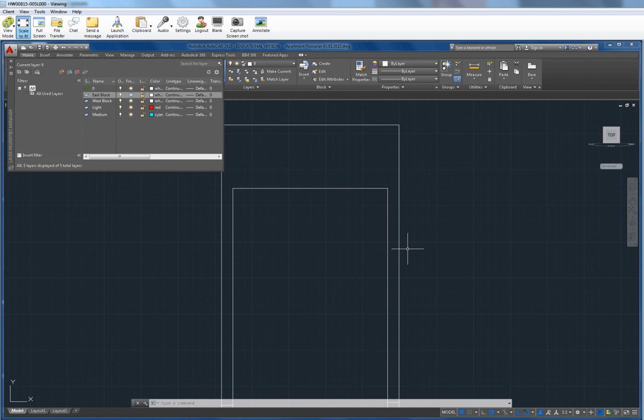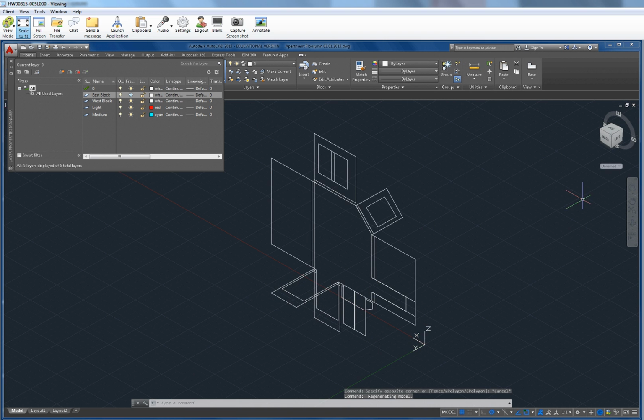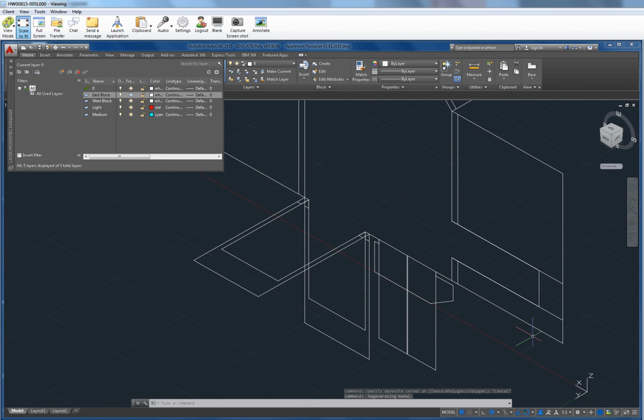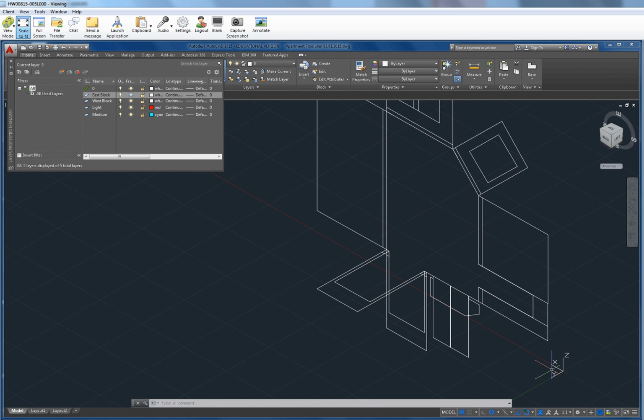Now the other issue that you might run into is where the UCS is placed in relationship to that. So we might be drawing, and it might not be where we think it is, and this is where it gets sort of funky when we reorientate this. But based on where the position of the UCS icon is, and we haven't really talked about this so much, we can change the origin. I think it's asking for origin.